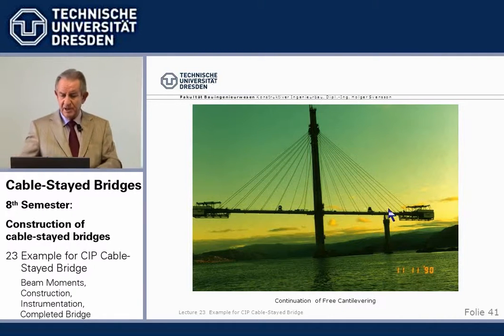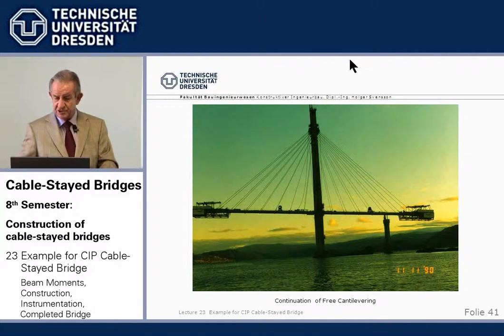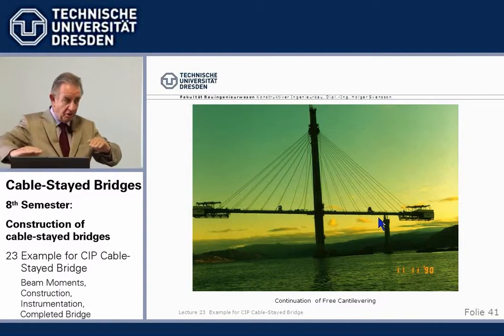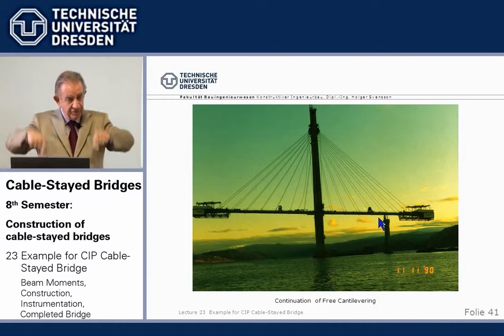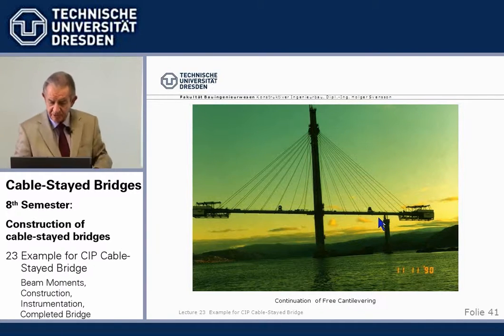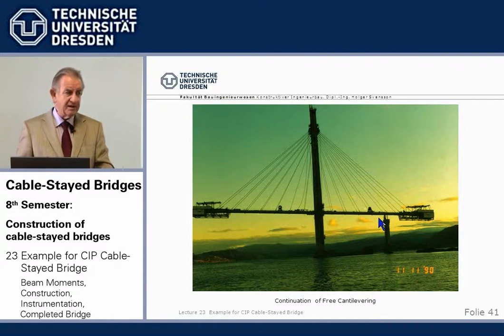So we had this auxiliary pier here which has a vertically sliding connection. So it takes only horizontal forces, but not vertical, because otherwise we would have a hard spot in our elastic supports and we would have a kink of moments and all that. So that's where it was. At the end of construction, it was detonated and served as a habitat for the fish.